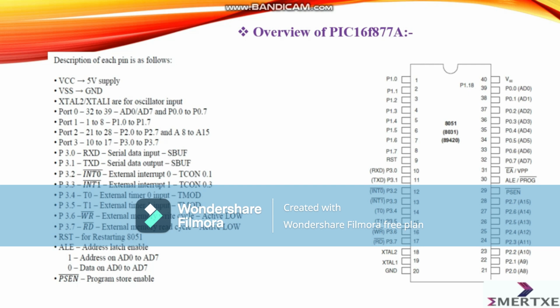XTAL2 and XTAL1, pin numbers 18 and 19, are the oscillator inputs. Pin number 20 is grounded. And the next important one is address latch enable, which is pin number 30 and is programmable.